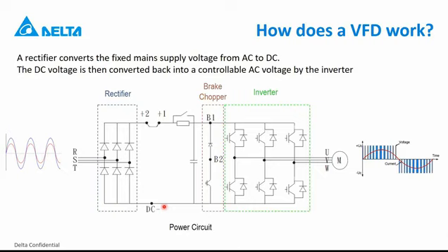But it's important to mention that this function will only actually work when you are running a motor. At very low loads, it's impossible to detect because then you also have very low ripple. But as soon as you start adding some load, then the drive will detect that. It's very easy to do.